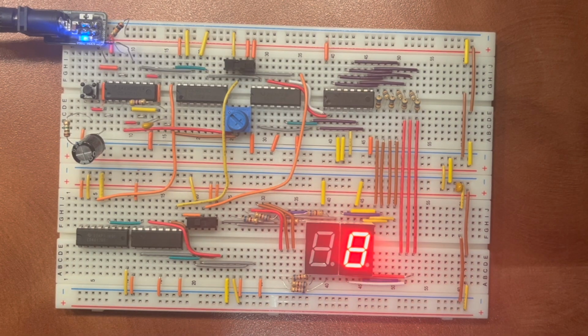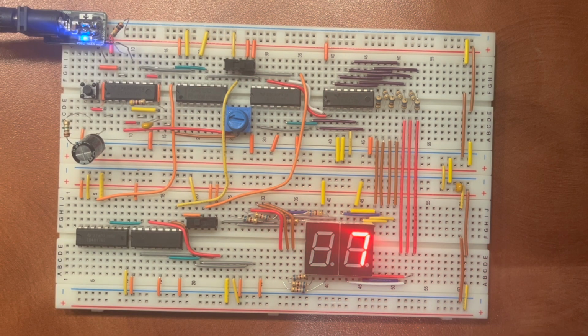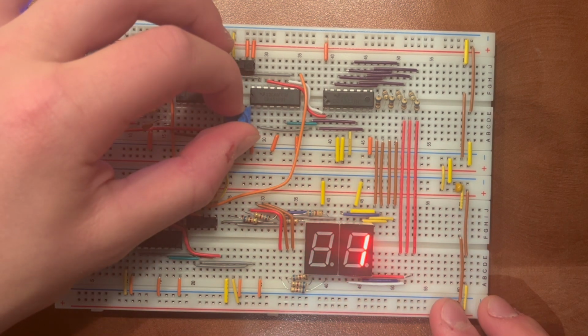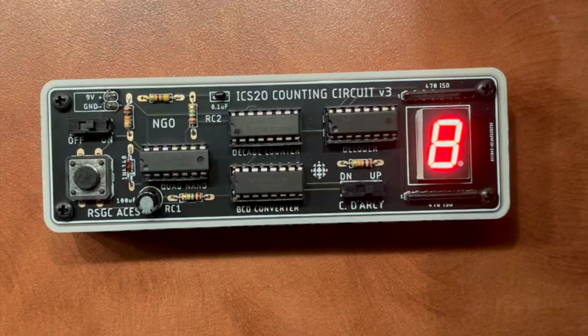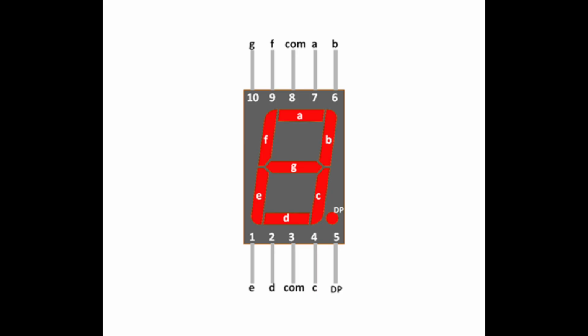Additionally, this circuit also allows for a potentiometer to be a replacement for the 330K resistor in the RC2. It can change the speed of how the circuit counts. The 7-segment display is used in the counting circuit to display the number which is received through the 4511 chip in binary. It includes inputs for the segments labeled A to G, which match the 4511 IC.